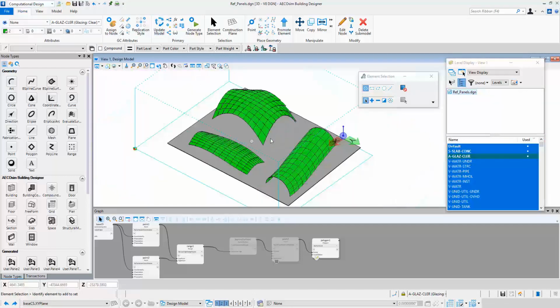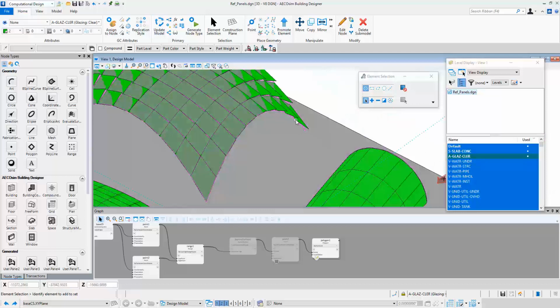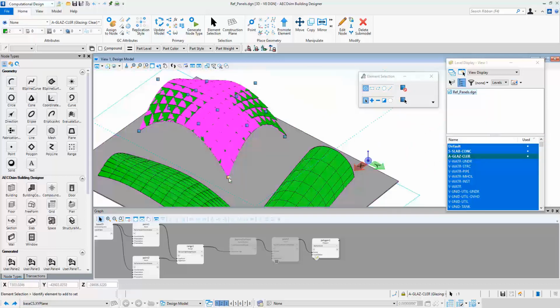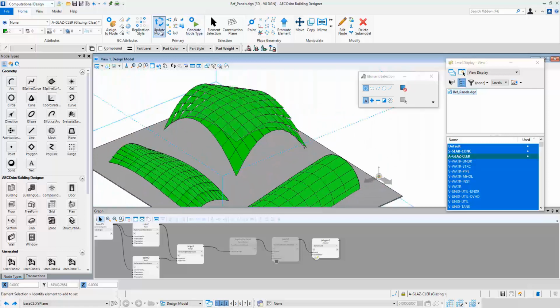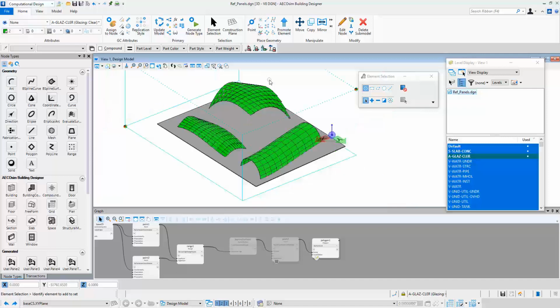Okay, it's the same again with this guy over here. Let's select the underlying surface and we'll just hit the up arrow there. So we move it to there. You can see the surface is transparent, just sitting under there like that. And again, we can hit Update Model and the panels move to suit. So we're combining our normal day-to-day parametric modeling with our computational design modeling here.